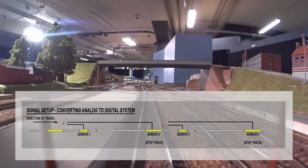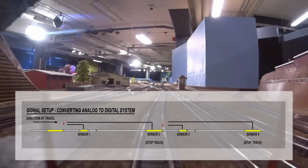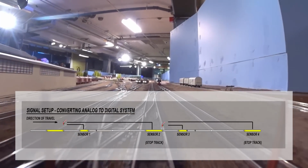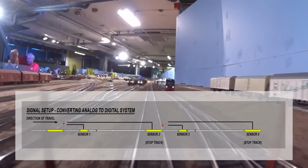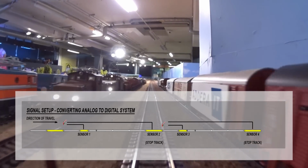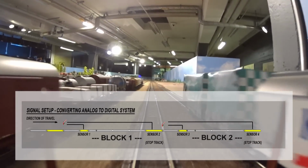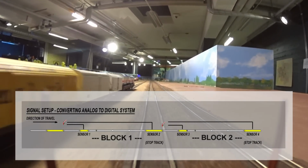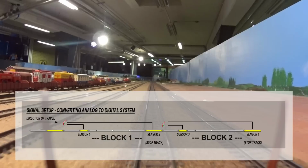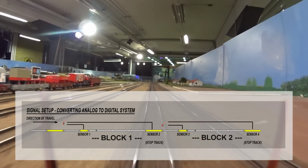So if we now want to convert this to a digital system, then we have plenty of isolated tracks with a separate feed to choose from when choosing sensors. And I typically do like this. The first sensor is the old red analog one, and the second one is the stop track. Now, in the digital system, you don't have to switch positions of the sensors to assure that the train is fully into block 2 before block 1 gets released for new trains. And that is because this is solved in the software.